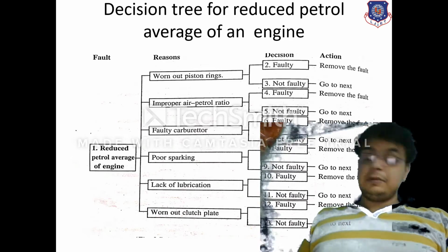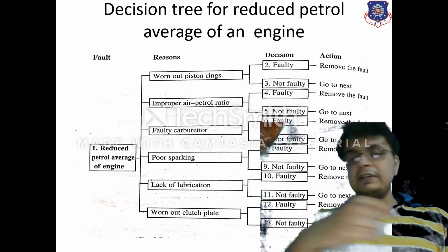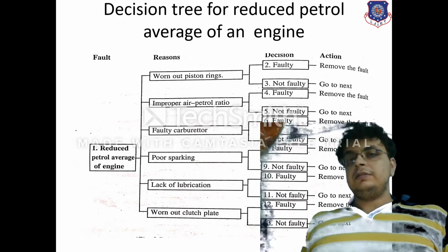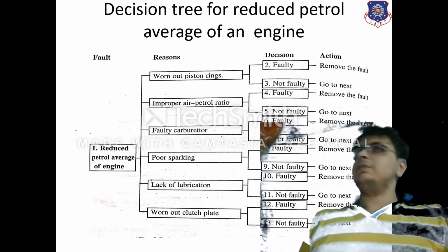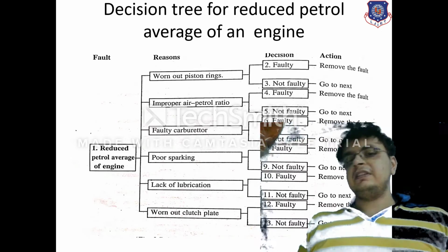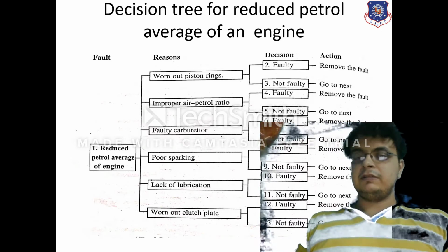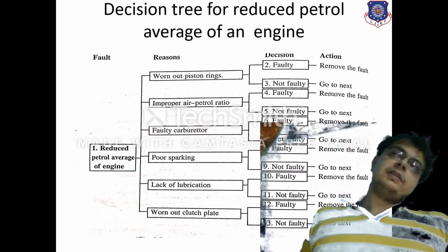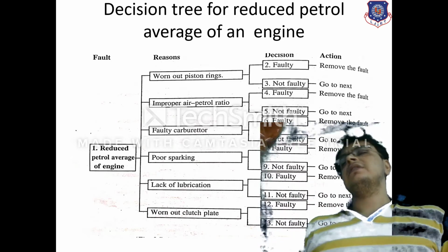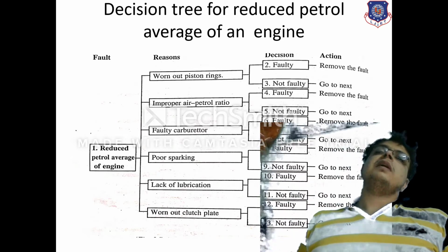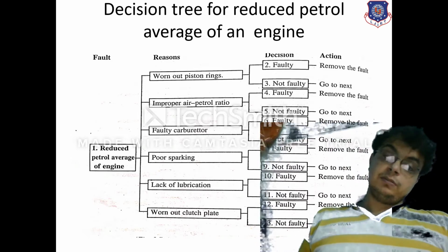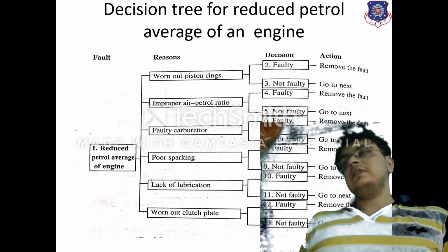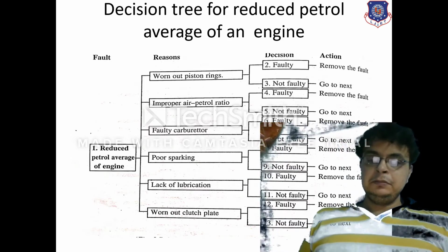Faulty carburetor is very much important. If it is faulty, the reduction in the average of the engine can also happen. Poor sparking. If the sparking is not proper to the required extent, then also the failure can take place. Lack of lubrication. Insufficient lubrication is very much harmful to all the motors, to all the engines. So proper lubrication should be done. There should not be any lacking in the lubrication.